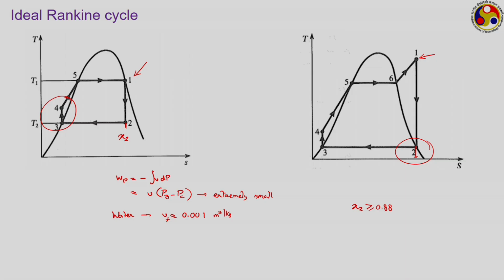Now, both these cycles are ideal cycles, where we are not considering the irreversibilities which can be present in the compressor and pump, and also the pressure drop which the fluid may experience while passing through the boiler, the turbine, or the condenser. The effect of isentropic efficiency we have seen through a numerical example. Let us see the effect of all such possible practical difficulties in another one.